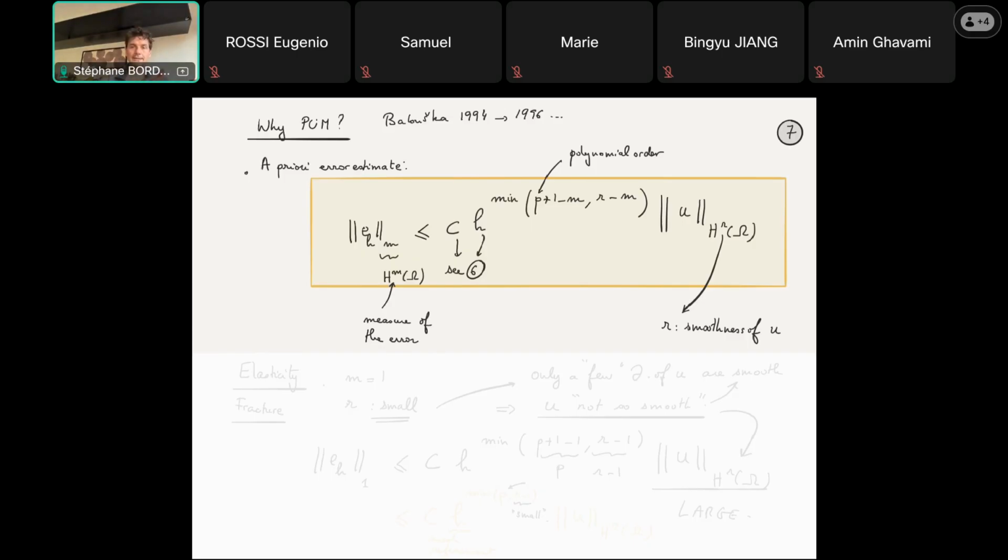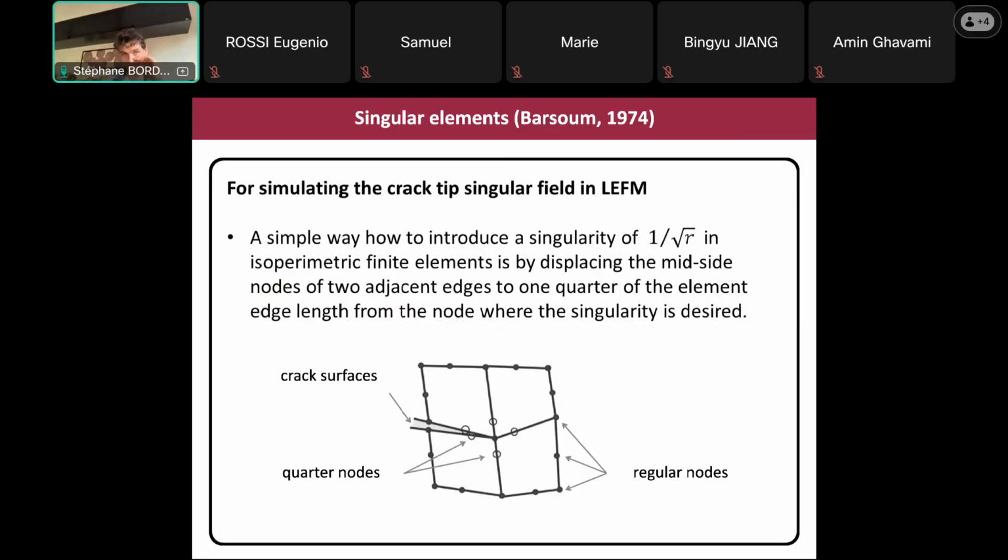So the smaller these values, C times norm of u, the lower the curve or the line will be, which means that the error will be less. If you have a very large norm of u, then you'll start high, right? So same slope, but you will start at a higher error level, meaning you will need more elements to get to a certain error that you require.